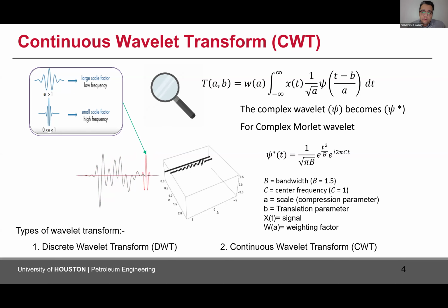This continuous wavelet transform provides a magnified version of the data embedded in our signal. This convolution can be done through two main processes. The first process is scaling, which is the compression or stretch of this short wavy signal, and translation by moving this wavelet over the signal to magnify its content.